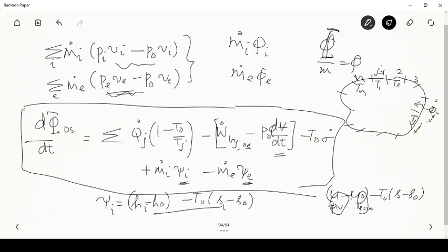Okay, so this is an equation for exergy balance, and this equation is very similar to your bank balance analogy equations, the conservation equations that you wrote for the case of mass conservation and energy conservation. But there is also a clear similarity. In the case of the second law, there was a non-conserved term in the form of generation of entropy. Entropy is produced due to irreversibility. Here there is an exergy destruction due to irreversibility.